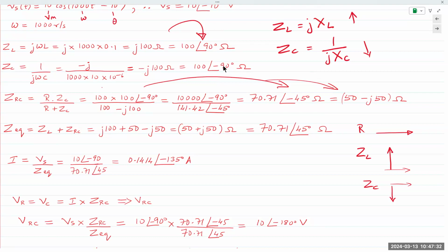Okay, I want to point this out because I remember similar questions being asked in previous quarters. In one lab it was 180 degrees out of phase, and you also mentioned in class it was 180 out of phase. Why is it not 180 out of phase? That's the reason: it's not in series. It's not sharing the same current or the same voltage, right? The voltage and the current for the capacitor and inductor are different.